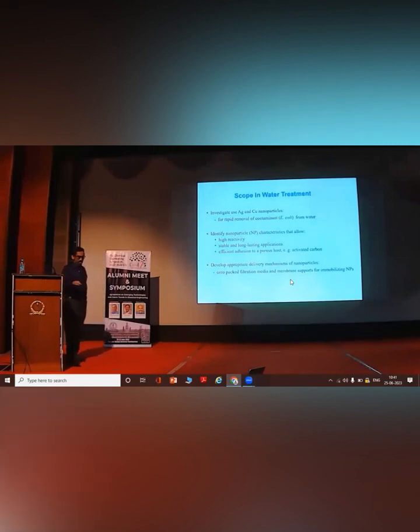Coming next to the second story, which is water treatment. So we were interested in nanoparticles all the time. So we optimize conditions for high reactivity, stable, long-lasting applications, and identify characteristics of particles by which you can put these particles on substrates, because only particles will flow out and will not last long, but immobilize them on surfaces like carbon, for example, which is a universal water filter medium.